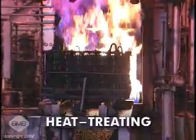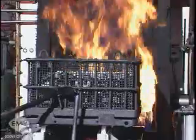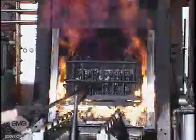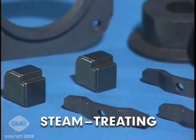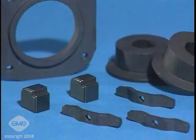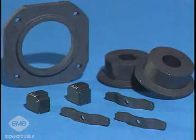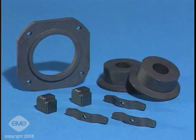Heat treating is used to modify a part's properties. Surface hardening increases wear resistance while maintaining toughness at the part's core. Through hardening increases overall strength and other mechanical properties. Steam treating develops an oxide surface coating, which increases wear resistance mainly, but also the strength and rigidity of ferrous parts. In addition, steam treating reduces some internal porosity and all surface porosity.